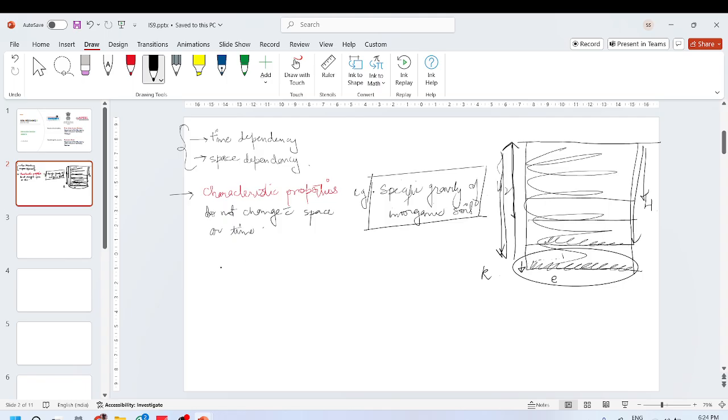What we do in classical soil mechanics is we assume that this layer has a permeability of K, a constant permeability. But in actuality, for example, when you are constructing a dam, you construct the base and you compact. Then you construct another layer, you compact. You construct another layer, you compact, isn't it?